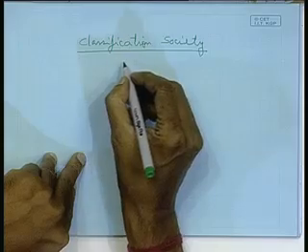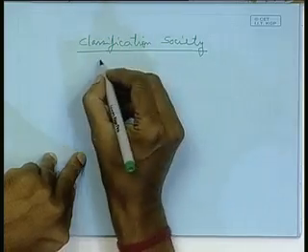So, in the first stage when you go for design approval, one of the designs is the midship section design, right, details of the midship section. That is also important, because that is the so-called backbone for the longitudinal strength, right. Okay, since we have written classification society, there are various classification societies.